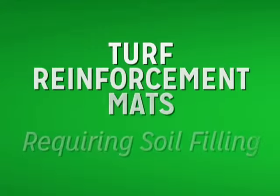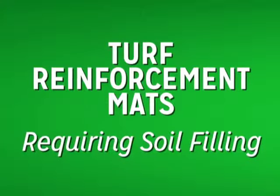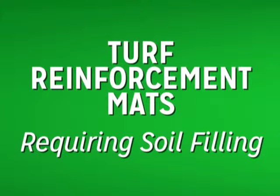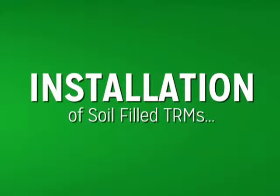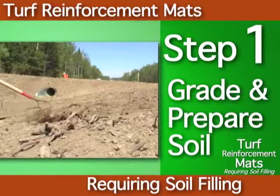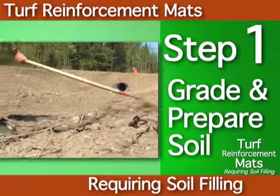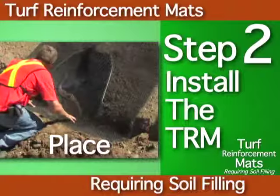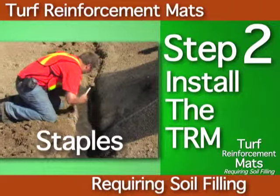The method just described works for degradable RECPs and turf reinforcement mats that do not require soil filling. If soil filling is required, the basic installation steps remain the same. However, there is some change to the sequence of installation. For turf reinforcement mats requiring soil filling, the first step is to grade and prepare the soil surface. The next step is to install the TRM as previously described.